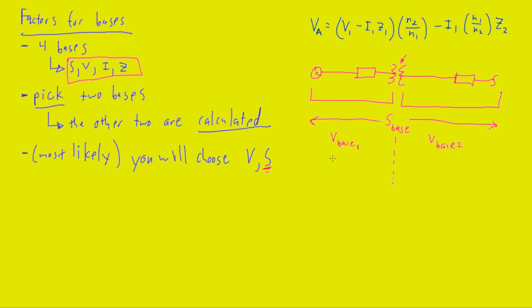And we know formulaically, the V equals IR sort of formulas, that current and impedance are derived from or are composite of voltage. So we can see that those bases will be just as likely to be altered or changed in some way, just like the voltage will be once it passes from one section of the circuit on one side of the transformer to the other. That's why you can derive the other 2 by means of calculations. P equals VI and V equals IZ here are ways that you can calculate bases after you've selected the 2 that you want to work with.